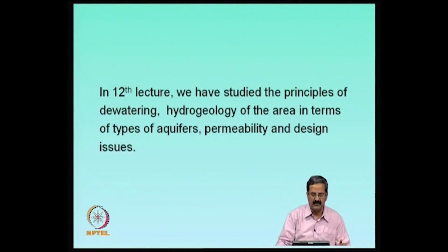foundations. Essentially, for dewatering, we should be able to understand the hydrogeology of the area. As I just mentioned, the aquifers we have, in fact we studied this in our undergraduate curriculum, in which you have two types of aquifers. One is a confined aquifer, the other one is an unconfined aquifer. You also have a perched water table, where the water tables exist in some localized areas, and so one should be able to understand the hydrogeology of the area and also the permeability, because this is an important parameter for design,